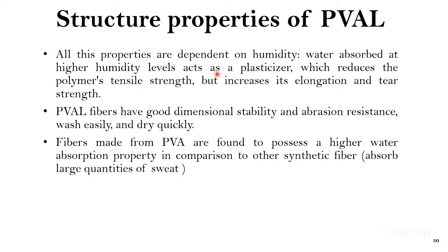So this plasticizer will reduce the tensile strength because it will make it softer. This polyvinyl alcohol becomes much softer in nature. That is the reason the tensile strength will be reduced, but the elongation and the tear strength will be increased in that case. So with PVA we generally have to take care. We can't keep PVA in open places for a longer period of time.